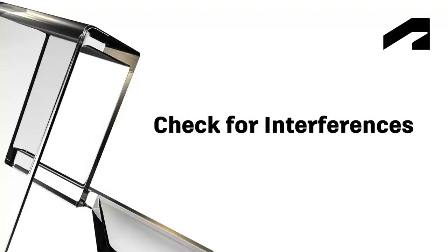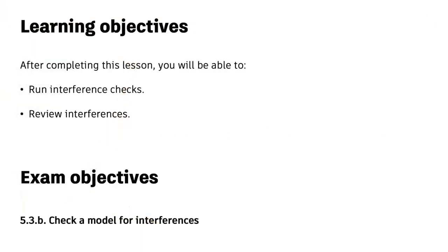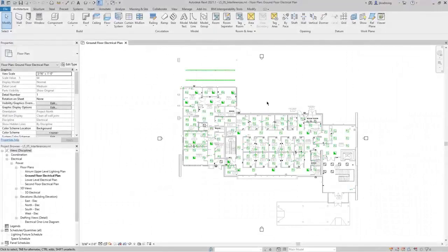In this video, we will cover running interference checks and reviewing interferences. When working in Revit, it's important that you coordinate with other disciplines, others on your team, and even yourself. You can do this by running interference checks. Let's take a look at how this works.